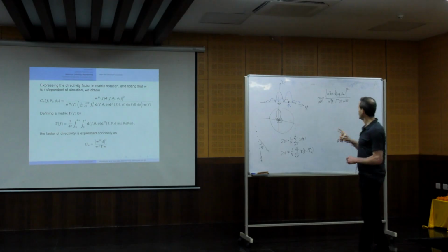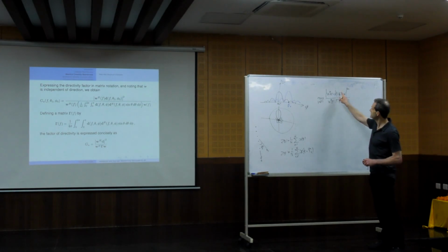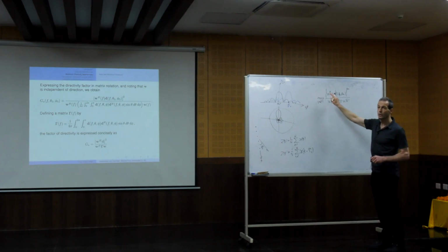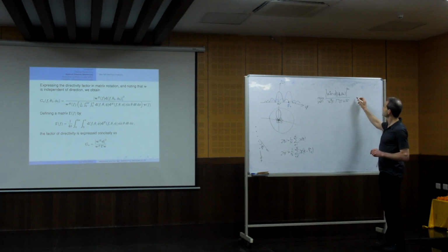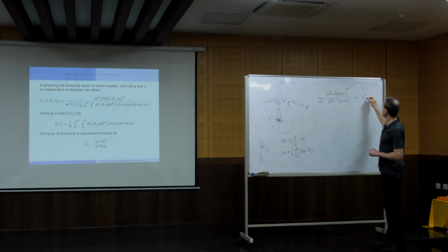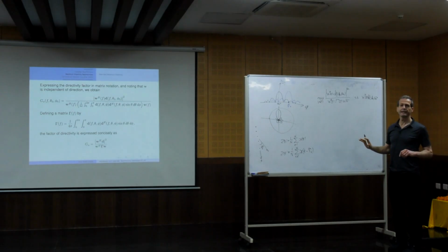But we also need to put a certain constraint that the desired source gain will be independent of frequency. So it's subject to W^H(f) d(f, phi_s, theta_s) equals a constant.